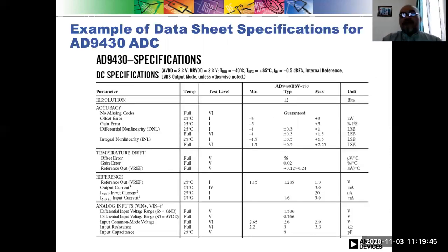So this is an example of datasheet specification. Yeah. So this is for the 9430 ADC. Here the resolution is 12 bits. So in 12 bits, the full scale range will be divided into 2 to the power of 12. Or how much is that? I think it is...